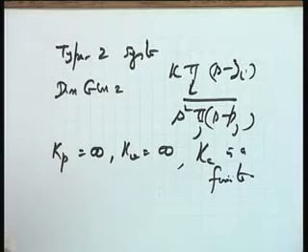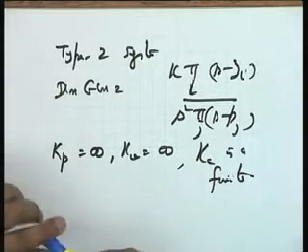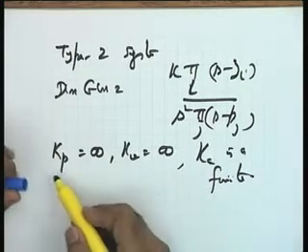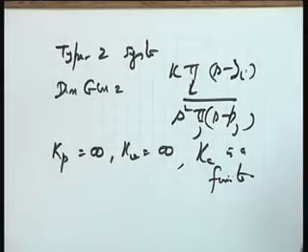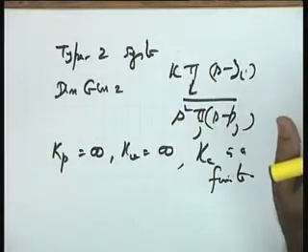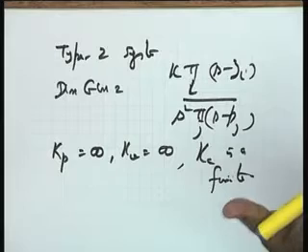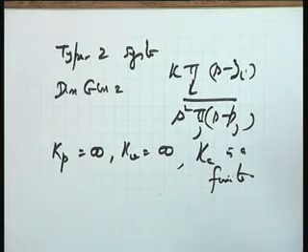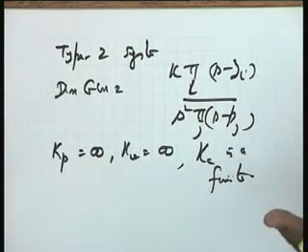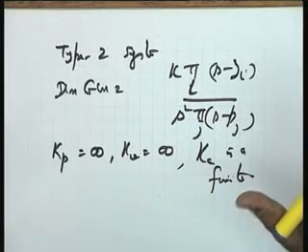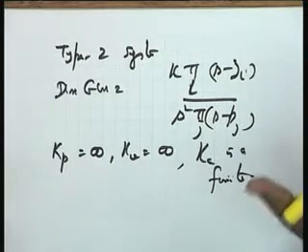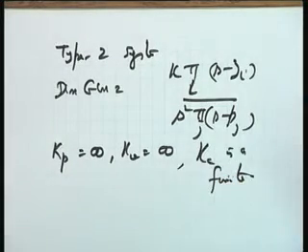In typical industrial control applications, I will say you are mostly satisfied. General statements I am making, very general application where the user has not given a very specific demand to you. In that case, I say that you are mostly satisfied with 0 steady state error to step inputs and finite steady state error to ramp inputs.